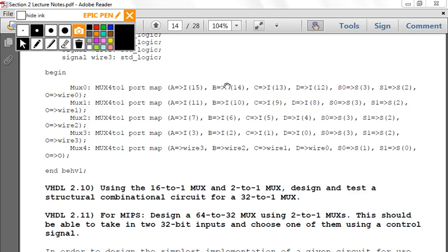Because you have 1, 1, 1, 0, 0, 1, 0, 0, if I remember correctly. But you want this specific value that you select mapped here. So if you switch this around, you get S0 mapping to S0 and S1 mapping to S1 here, then you'd switch the inputs. The key thing with a multiplexer is understanding the concept of, based on these select signals, I want this output.